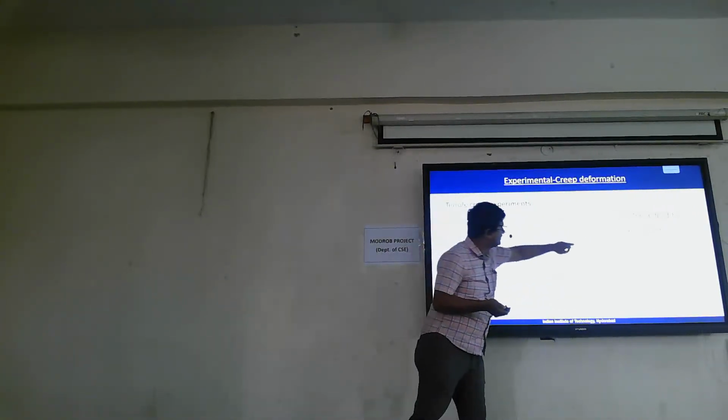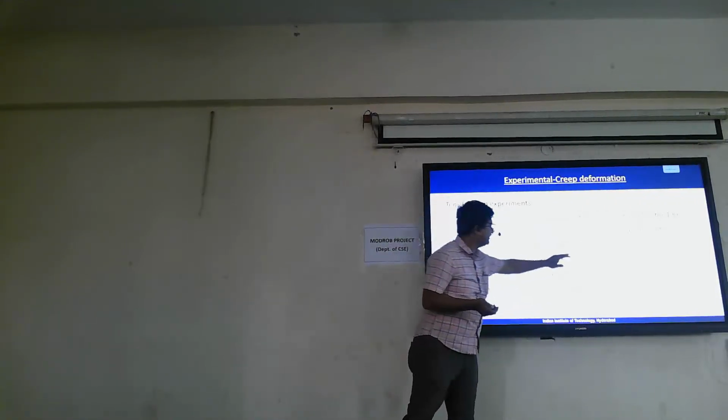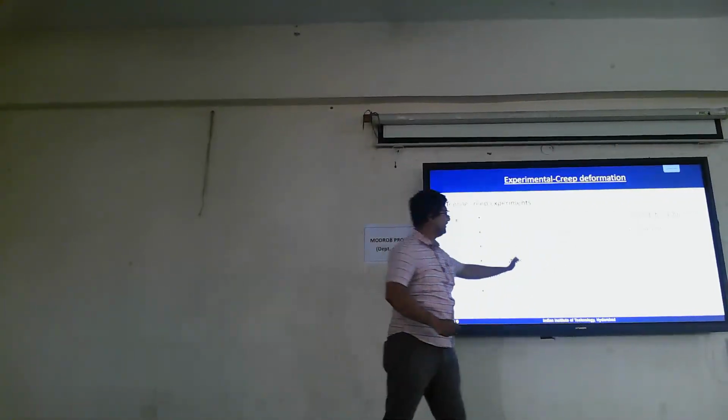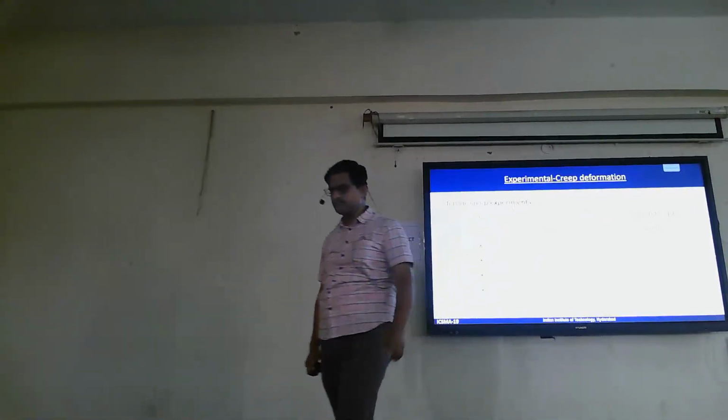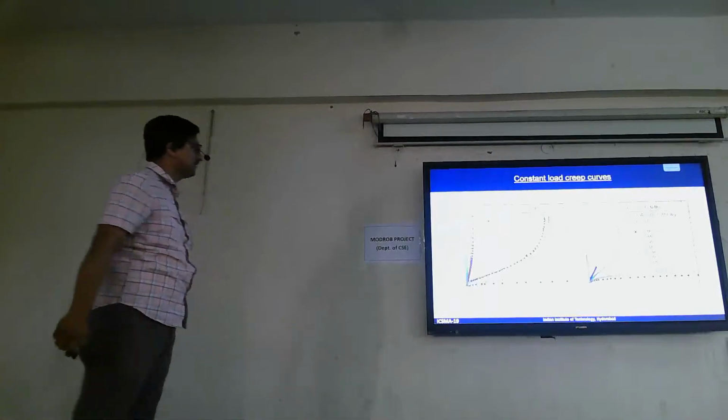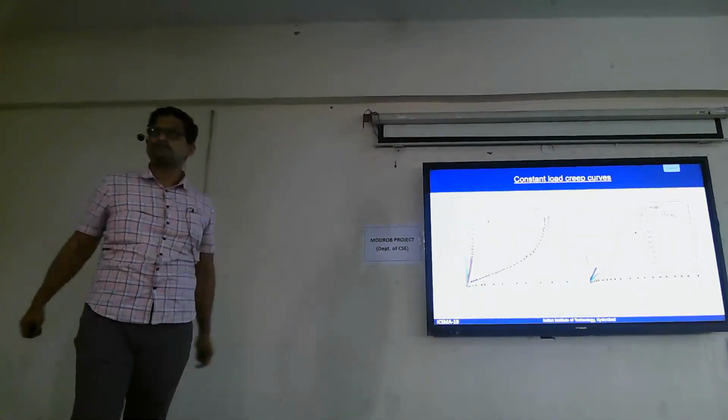The temperature is between 700 and 800 degrees, and the initial stress ranges over different constant stresses from 50 to 300 MPa, and the initial grain size is 9 micron, and we looked at the microstructure using SEM and TEM. I think I can show them. This is the creep curve.